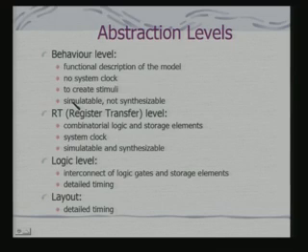That means I can have a behavioral simulation, but I cannot really synthesize, because until the timing constraints are known, I cannot synthesize. What does synthesis mean? Translating this functional specification to actual hardware blocks in terms of gates, and even at the lower level in terms of actual transistors and their implementations.